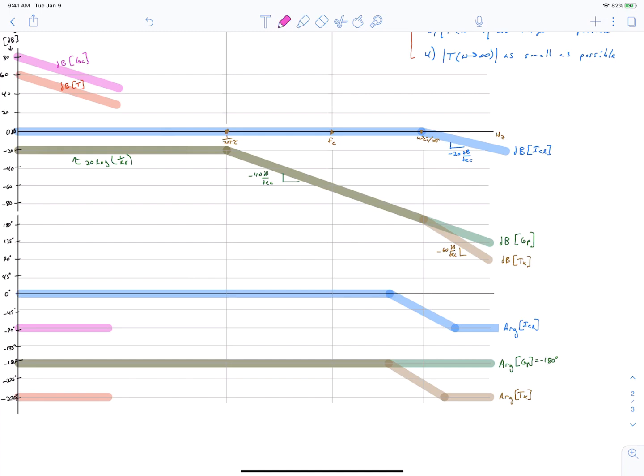One is that the kernel of our loop gain is always below the 0 dB point. We have no 0 dB crossing. So that means that we're going to have to design our regulator to boost up the kernel of our loop gain so that we can have a 0 dB crossing in our loop gain. And we can see that we're well on our way. The loop gain that we're starting to draw here clearly is going to cross the 0 dB point. And we want that to happen at the frequency I've labeled out here as FC.